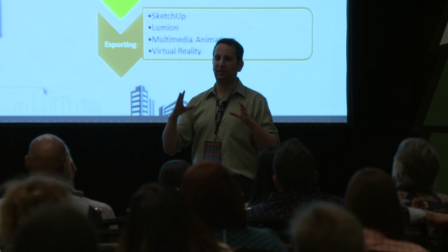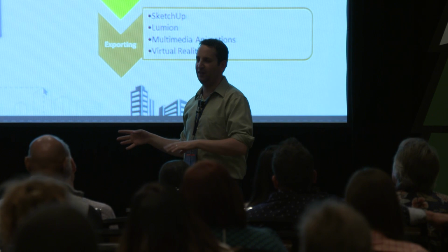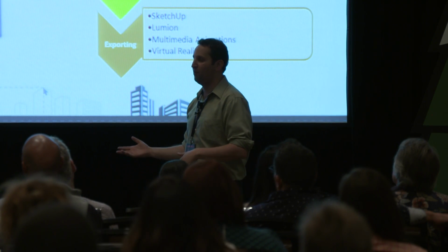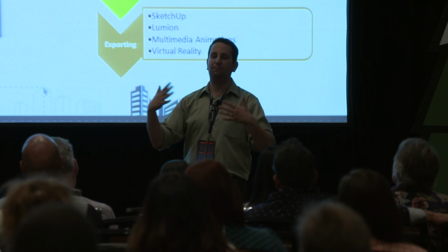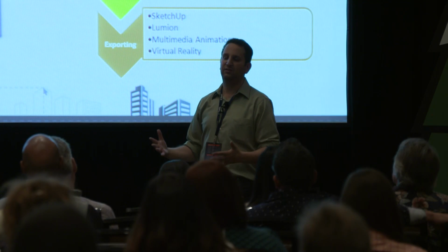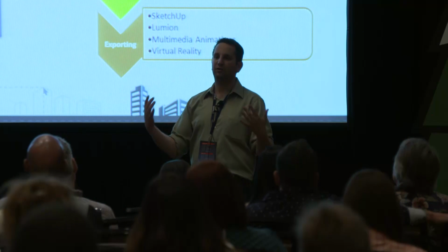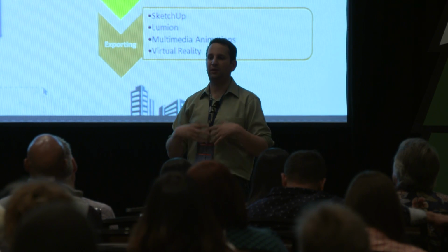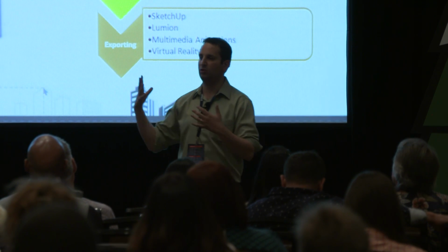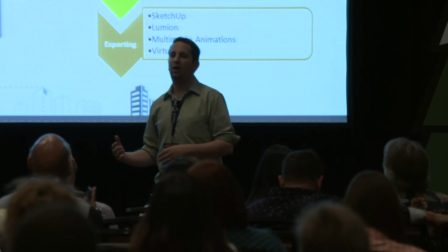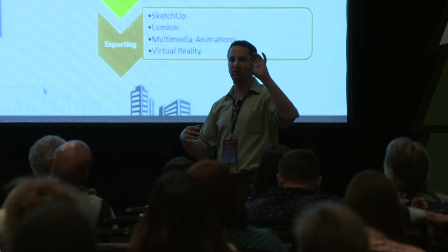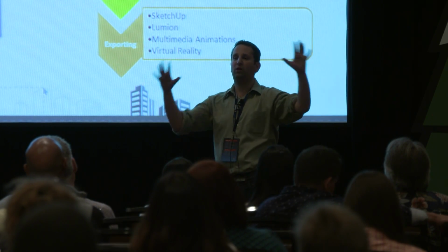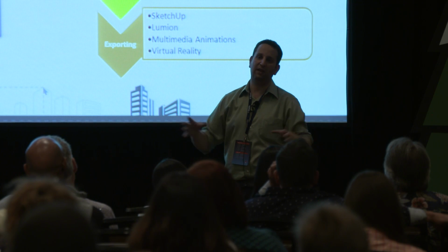So I'm actually, since we started using Lumion, we've been actually less diligent about layers. What I have to end up going back for a lot of projects is going, because really the biggest reason to use layers in SketchUp was to organize all the geometry that comes in with vegetation. We put in thousands of plants, and you have to turn them off to actually use them so you don't hit your performance limits. At the end of the day, though, it's actually management of your project. So that's really the way to do it.